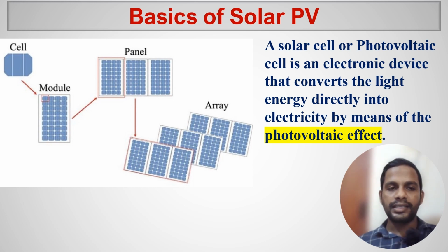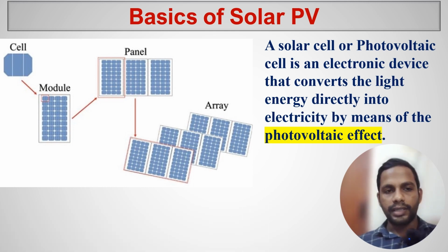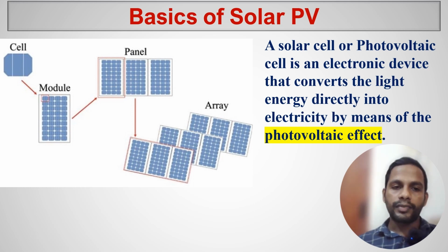The reason is that a solar PV cell is the smallest unit, which can generate 0.5 to 0.6 volts. That means a very small voltage. With that small voltage, we can't do anything. So we have to make this into about 12 volts, or 20 volts, 30 volts, 48 volts. There are different voltage levels. In order to make different voltage levels, we have to connect the cells into a module. That's the reason the module comes from the cells. Again, there is the question of how many cells are in the module; we will look at that in the next slide.